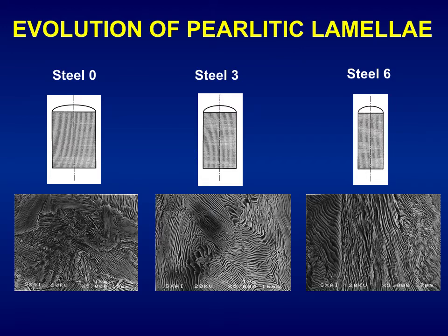It is like a composite material, a plated material, oriented in the vertical direction, the plates being ferrite-cementite lamellae, with a compact structure and decrease of pearlitic interlamellar spacing.